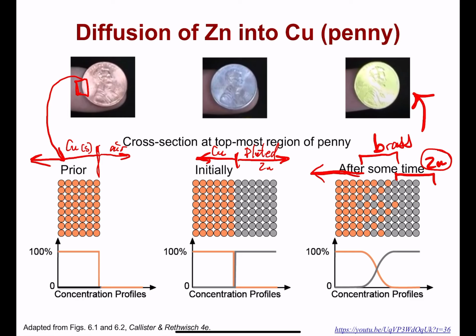fundamentals for non-steady state diffusion are going to try to fit these concentration profiles for zinc that I've just cartooned over here in red, where we build from no concentration deep into the copper, and we rely on that being constant for our model. And then we're going to see this sort of S-type curve. It's a Gaussian error function curve that is going to fit nicely by way of solving a partial differential equation.